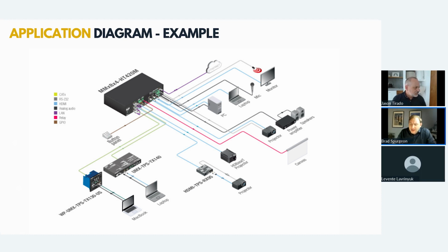So what I have right here in the schematic is a wall plate that is being PoE powered from the matrix. I have maybe an extender. Right now it's the UMX. It could be a whole variety of extenders also being remotely powered from the matrix itself. And then on the output side, I'm going into one of our HDBaseT receivers. Again, with that receiver and the Lightware matrix, I'm going to get that complete cable diagnostic, and then I'm converting that HDBaseT pulse amplitude signal back to a TMDS HDMI signal into the projector.